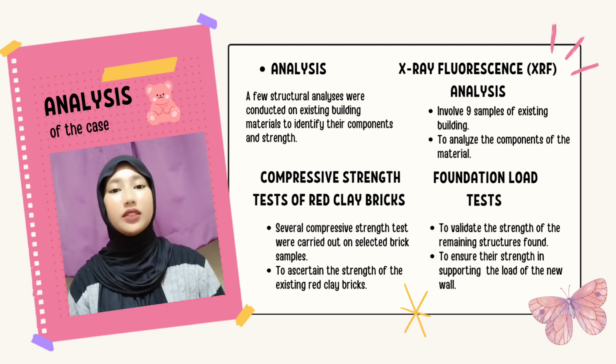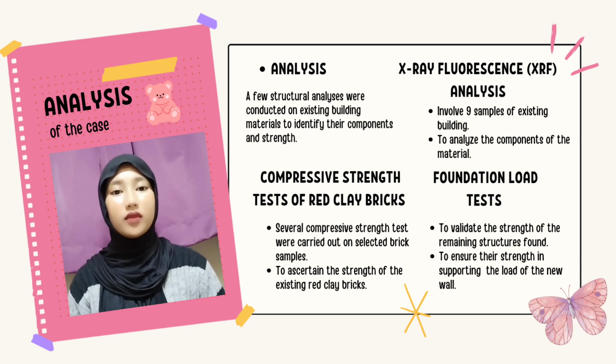The minimum test load was maintained for 24 hours and time settlement readings were continuously monitored and recorded. Loading was released gradually and the rebound readings were later taken.